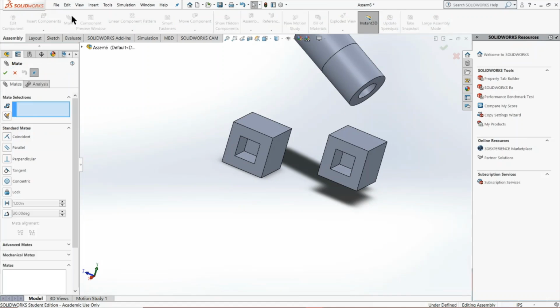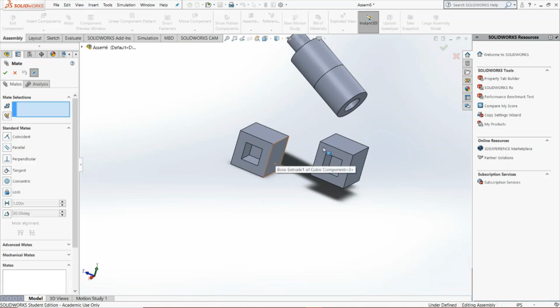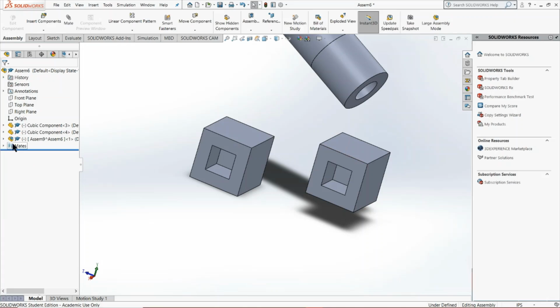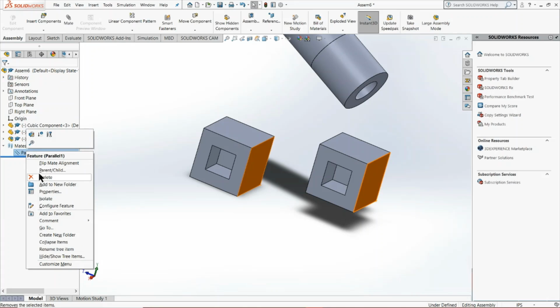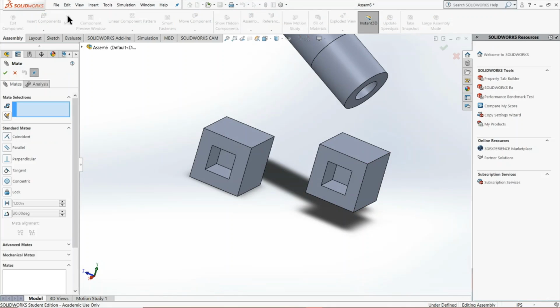The whole idea with mating is that with adding more mates, you're adding more constraints, you're restricting more points of freedom within your object or your whole assembly. So the more mates that you could give this software, the better your model will be, the more rigid it'll be. But I'll always advise caution when using these mates, just so that you don't particularly screw up regions of your model. So like there's instances where it creates errors for itself.